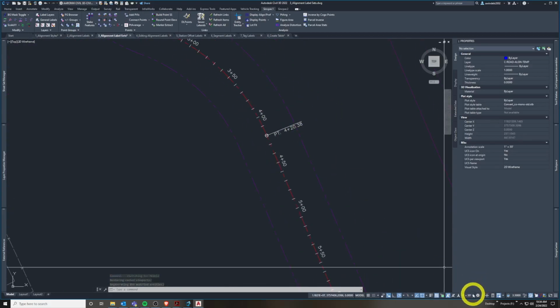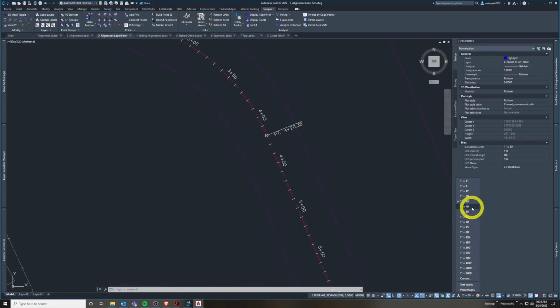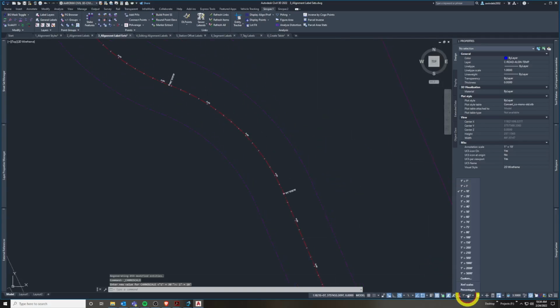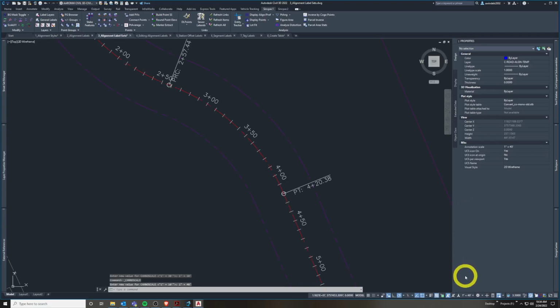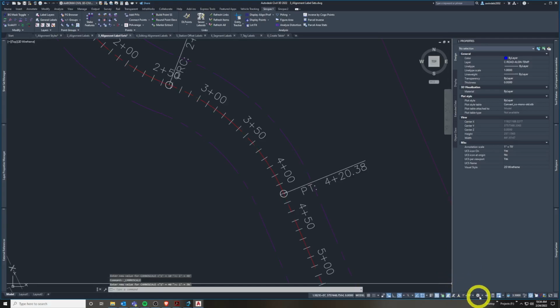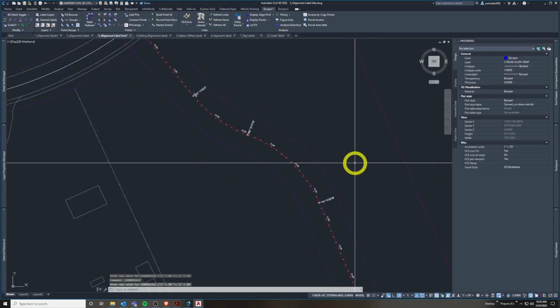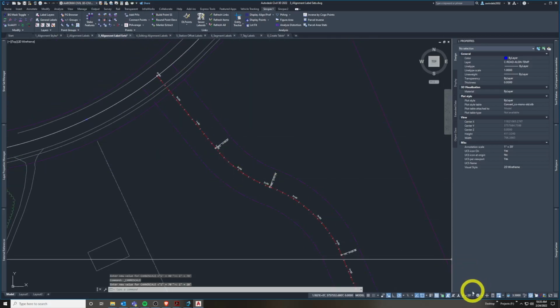Same goes if you go to model space in your global area, your whole drawing here. If I change my scale in my model space, this can be helpful when you want to just scale them down so you can see things. Turn 1 to 10 scale. I'll go to 1 to 40. I think that's where they were. They were at 1 to 30. If you keep going up, they keep getting bigger and harder to manipulate things. So let's go down to 1 to 20 just for fun. Show you how they got smaller. So that can make it more usable.